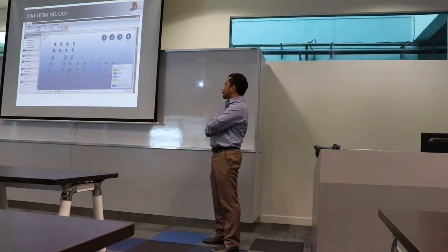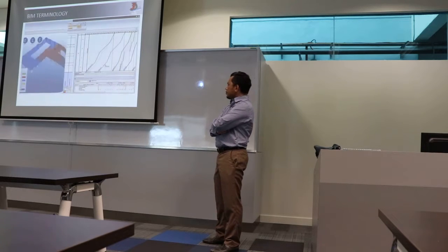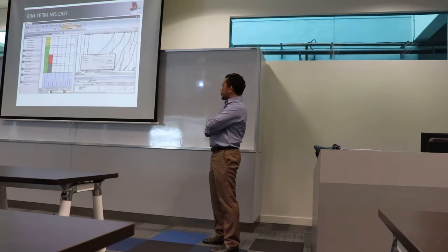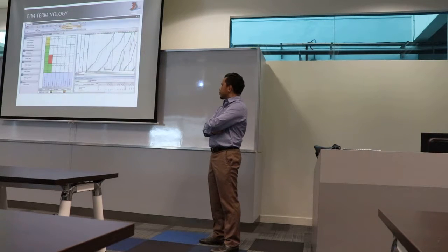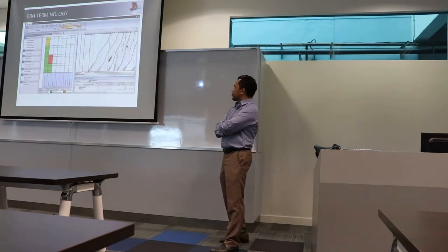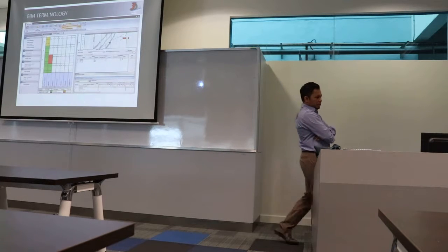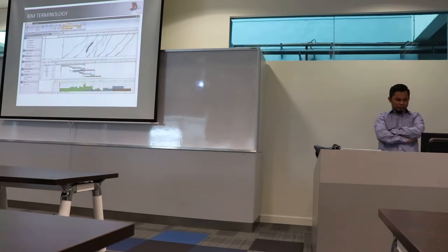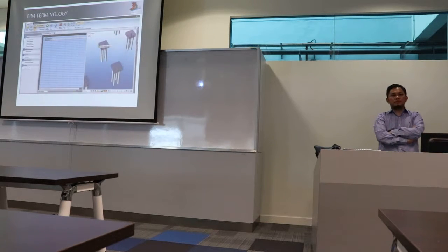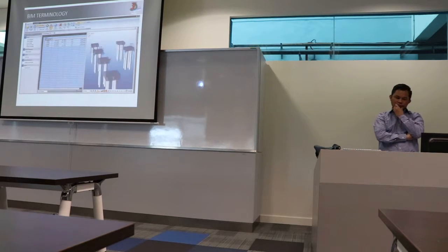As we move into the controlling phase of a project, we monitor progress against the target, review deviations in the flow line view, and automatically forecast the effect of not doing anything differently over the next few weeks. We can test control actions to define the best plan to correct any potential delays. Here we can see clearly that the subcontractor will need 4 crews in order to stay on target. By playing the 4D simulation, we can select the layout points for that week and upload them to the total station for the layout in the field.